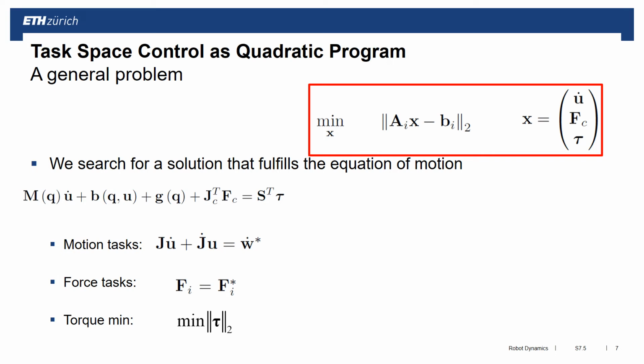Instead of purely doing inverse dynamics control with this support consistent dynamic description, we can also revisit the quadratic programming solution we looked at before, but now for the full dynamics equations of motion of a floating based system. Remember what we did last time: we looked at an equation.